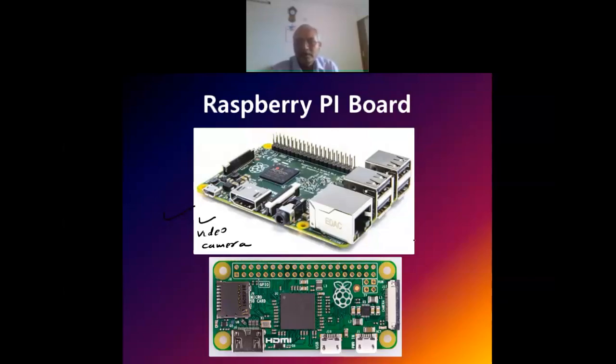There are USB ports available here, where you can connect different devices, like a USB keyboard, USB mouse. This Ethernet port is given here, so you can connect it with an Ethernet cable. Inbuilt Wi-Fi chip and Bluetooth modules are also coming in the advanced version, Raspberry Pi 4.0. This is the earphone socket which you can use to listen to music. This HDMI port you can use to connect any HDMI display. And this is a micro USB port where you can connect a plus 5-volt supply with the help of a mobile charger cable.